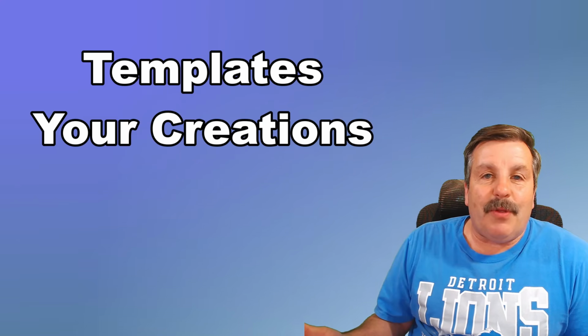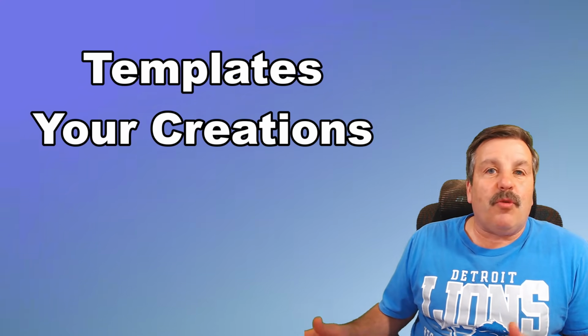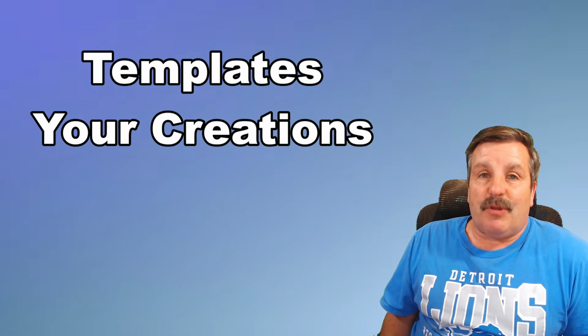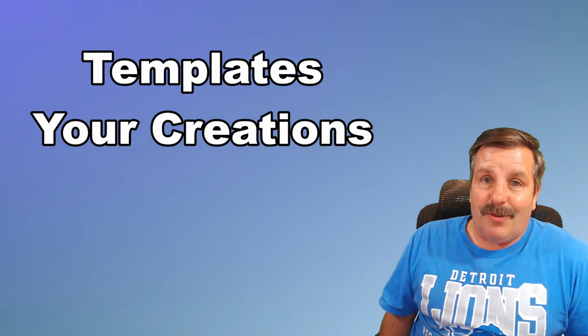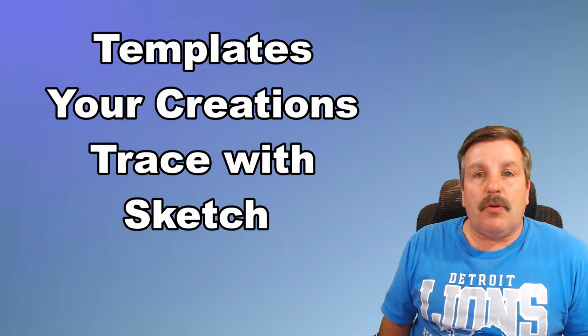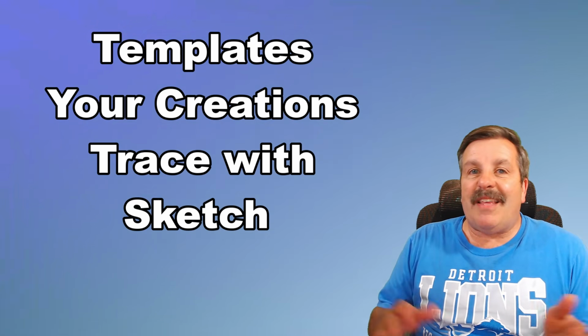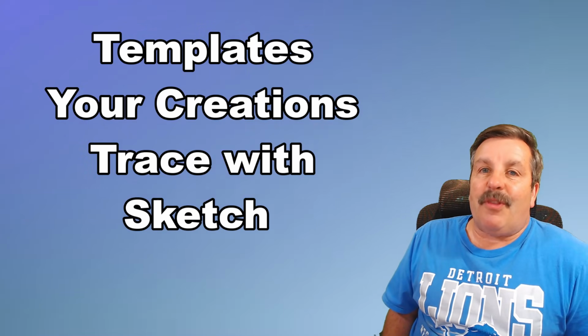All right, so let's quickly check what we learned. Of course, we got a template. Once we opened it, I showed you how to save things as your creations. When you revisit that area, you can always reuse those parts, which is super slick, especially with something like those fidget holes. Of course, we also learned how to trace an SVG using the sketch tools. That was cool because it gave us that outer line, which we could then use to trim and make things so they fit the way we want it.